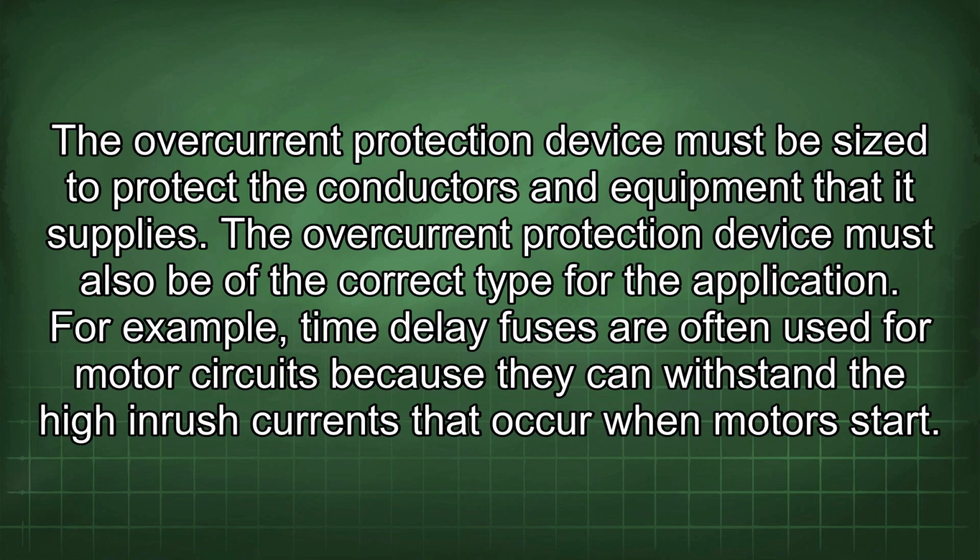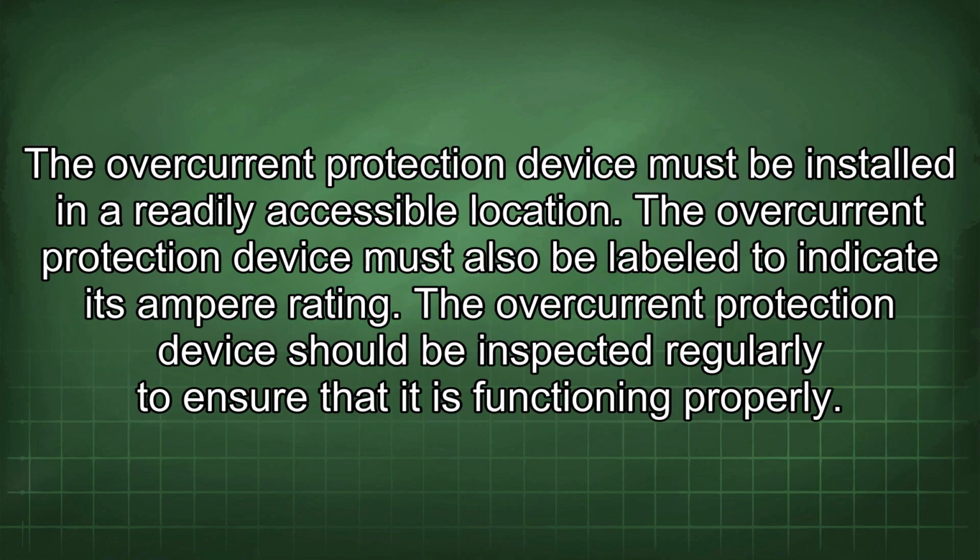occur when motors start. The overcurrent protection device must be installed in a readily accessible location. The overcurrent protection device must also be labeled to indicate its ampere rating. The overcurrent protection device should be inspected regularly to ensure that it is functioning properly.